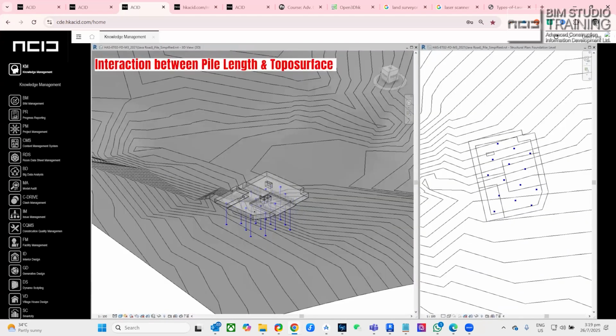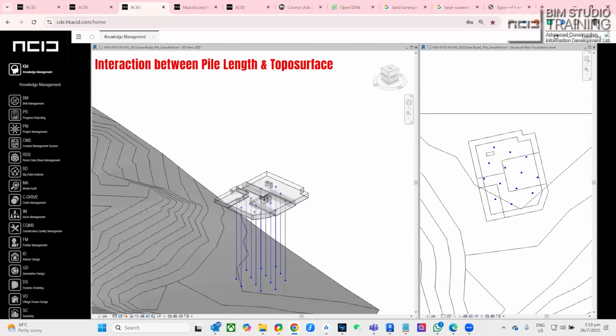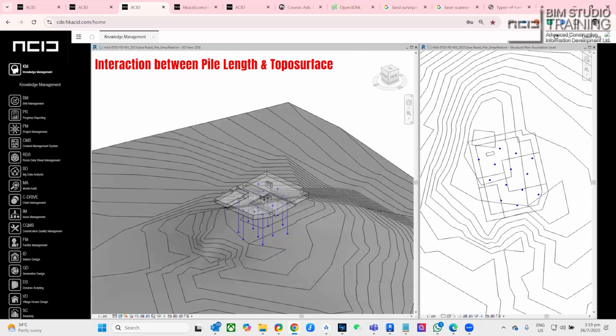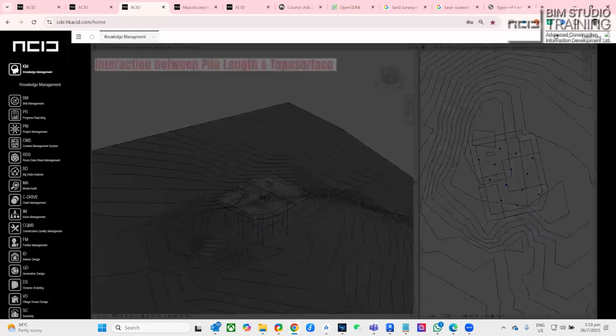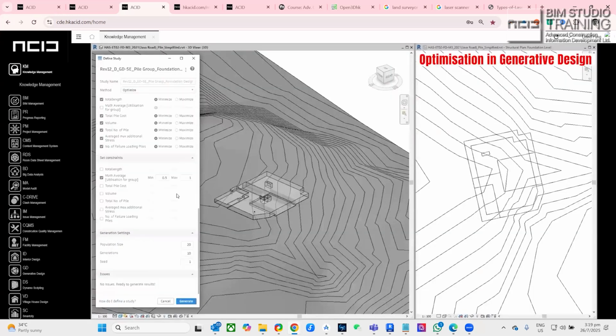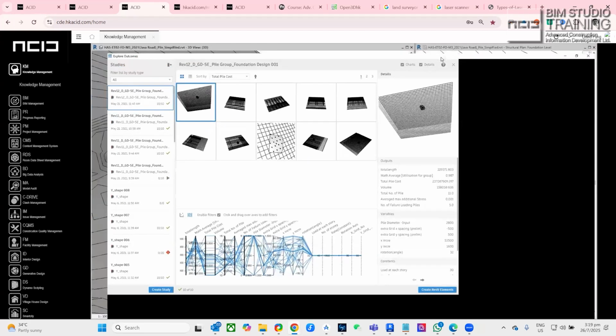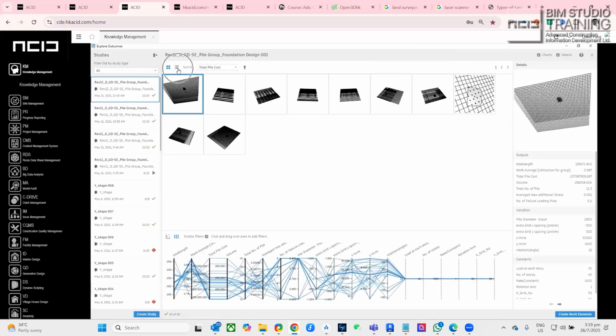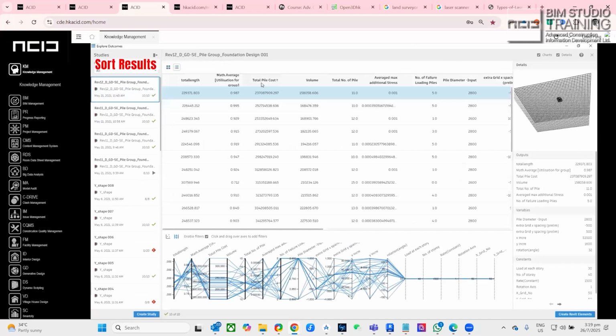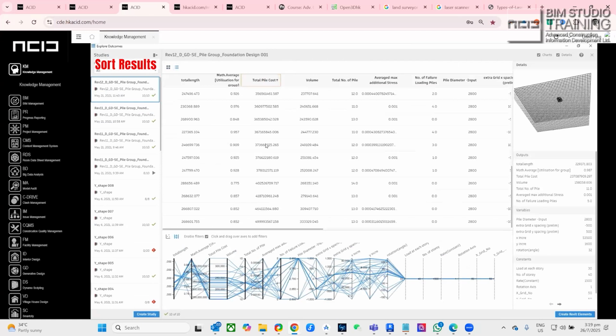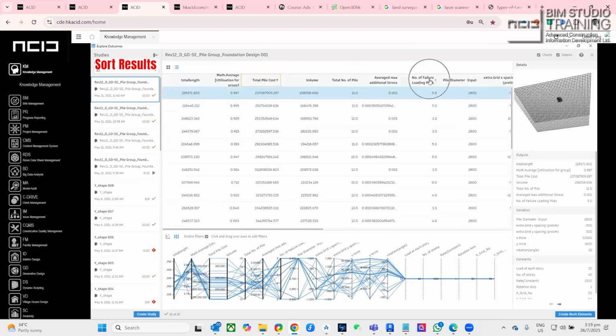So this is how we go. Put in different locations with different lengths, different configurations, and put in all these variables. We automate the process. We change the different combinations, and it comes up with a cost. Every single variation comes with a cost, and we choose the cheapest one. It will run for 1 hour and give us 3,000 of them. And here's the cheapest one. This is how the housing authority is using that for foundation design now.